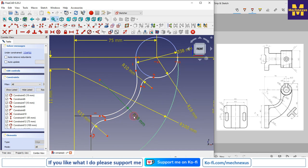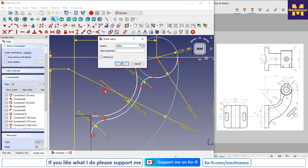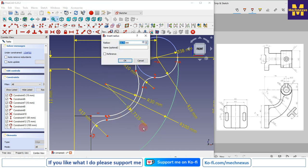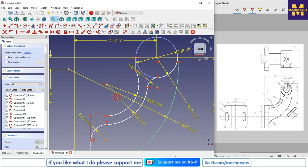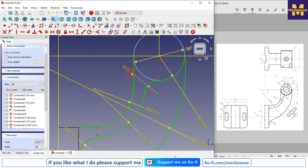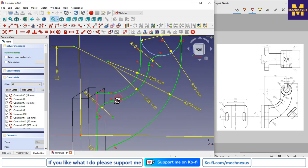So now I will give the outer one as 30. So I will give the radius 30, and this would be 38. So we have got the wall thickness of 8 mm. Now this and this would be the tangent. So now we have got our profile.